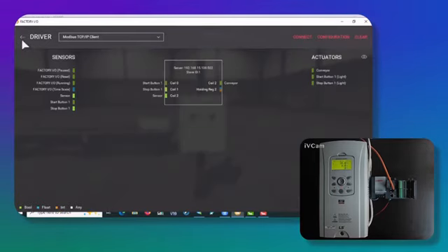Now my PLC is connected via a network cable using the Modbus TCP/IP protocol. It's connected to my laptop, which has the factory I/O software installed. Now if I've set up both of these correctly, when I click the connect option, you'll see that this green check mark appears here. This means that the factory I/O software is now connected to the LSPLC. So as you can see, it has also brought up the schematic for me here.